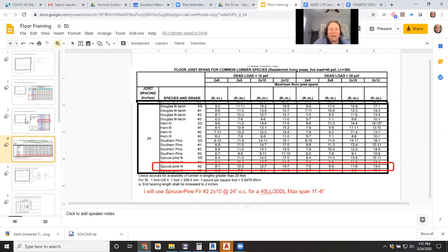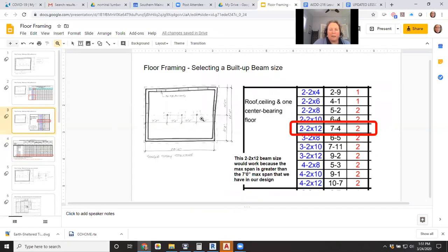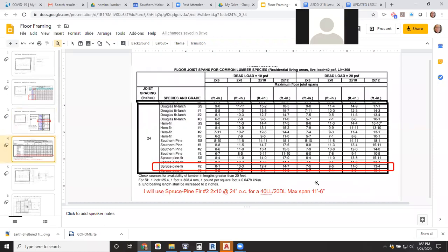So our worst case scenario would be that one of these sides would be 12 feet. I wouldn't care about the other side of 8 feet. I want to design the floor framing so it would work with the 12-foot side, correct? And then I'd know it is going to work for both. You'd be consistent for even the shorter spans?